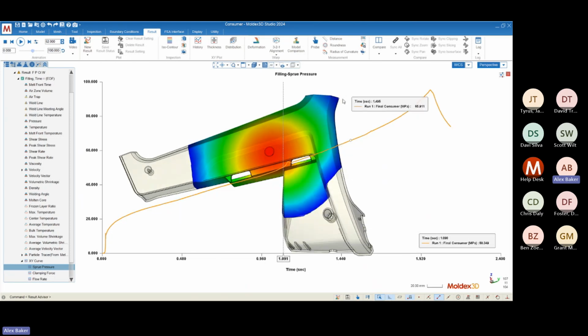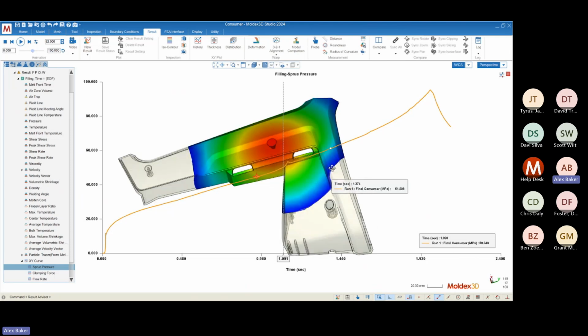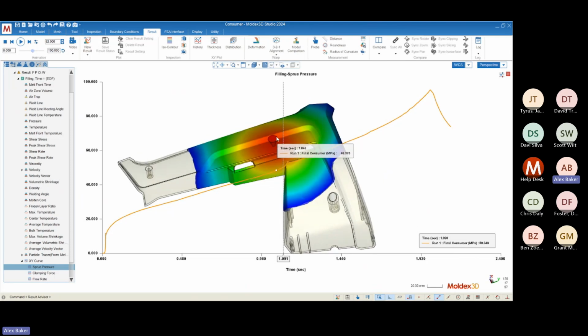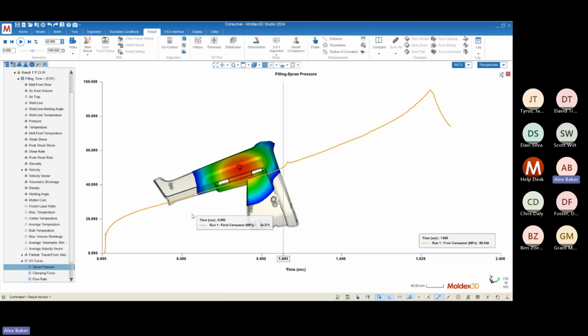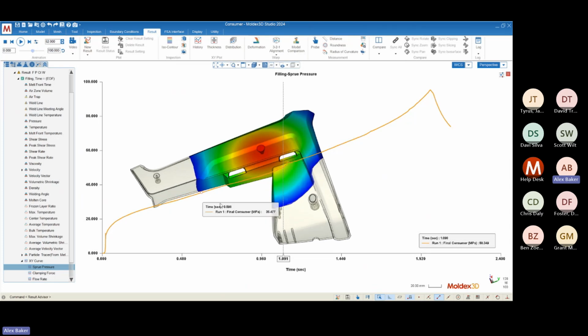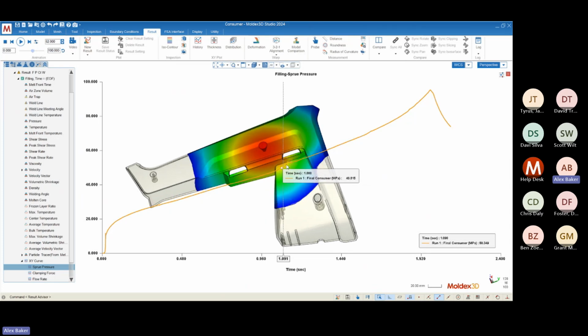It's kind of like water rebounding off of a wall. If you've ever seen water or a wave rebound off of a wall, when that rebound hits another wave, you get a big spike, or higher amplitude. That's kind of like what happens here. If that momentum shift goes through the melt entrance, then you're usually going to get some sort of impulsive pressure spike. And actually, in this case, the amplitude of this pressure spike is pretty low. Not really anything to worry about necessarily. It's just a little bump in the pressure requirement.